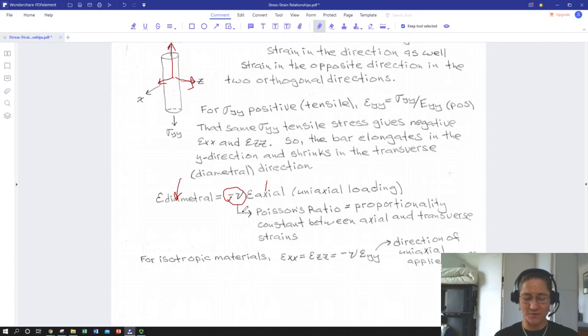This is not to be confused with elastic as in the elastic range where stress and strain are proportional, but elastomers, like polymers, rubbers. They tend to have Poisson's ratios close to 0.5, and fluids all do, and elastomers tend to behave quite a bit like fluids. Incompressible materials will have a Poisson's ratio of 1/2. So that's just something to keep in the back of your head.